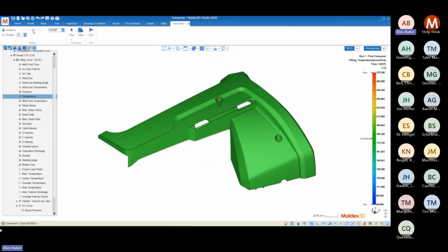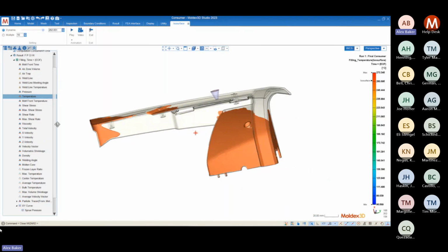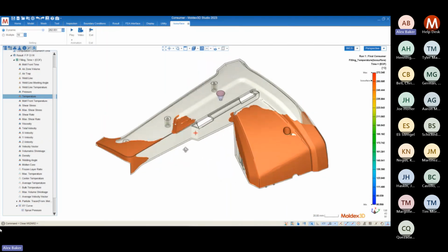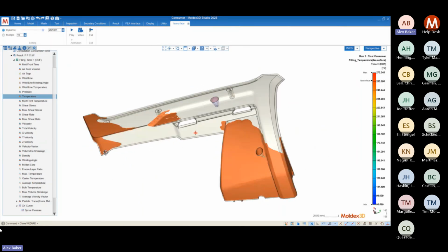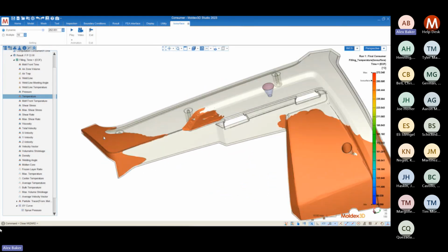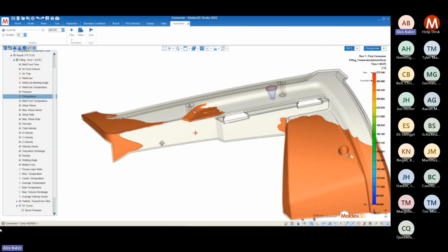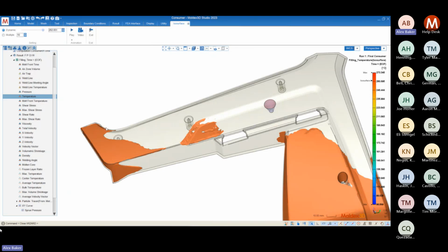And if I move the slider towards the right, or towards the hotter end of my scale, I'm going to see a bunch of the material start to go away, and only the hottest material will remain, really showing a good distribution or a good indication of where the hottest material lies in my geometry. And we can see from this, kind of like what we saw from the slicing tool, that the hottest material is in fact the end of fill.